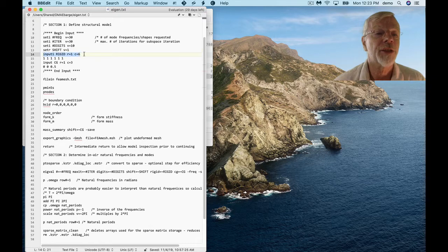I'll get to this. This is defining a 1 by 6 matrix or vector, and I'll get to what that means. And this defines a 1 by 3, and clearly, I think it's kind of obvious, I'm defining where the CG is. So I'm going to be using the inertial coordinate system, which has its origin on the still water line. And we already know from the example that the CG of this body is at 0.5, so 0.5 above the still water line. Remember, we determined the mass distribution to give us that CG.